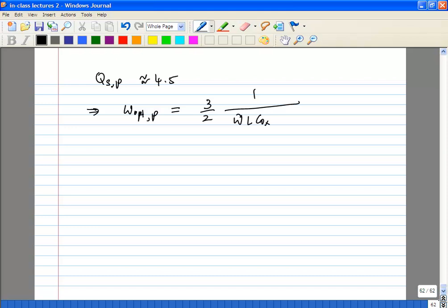This is omega C ox. So CGS is 2/3 WL C ox, and you put QSP equals 4.5. QSP is the power constrained QS, so it is QS after you have optimized QS, after you have applied the power constraint. It turns out that if you use a QS of 4.5, you can actually get pretty good noise figures for a given power.